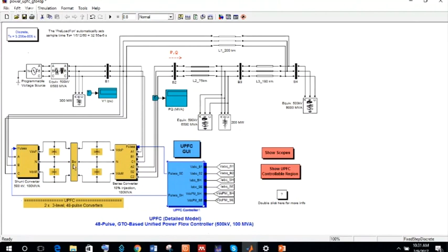And since the switch is closed, the shunt converter, as per these voltages, generates voltage and phase angle in such a way that the excess or required power is supplied by the shunt voltage source to the line.